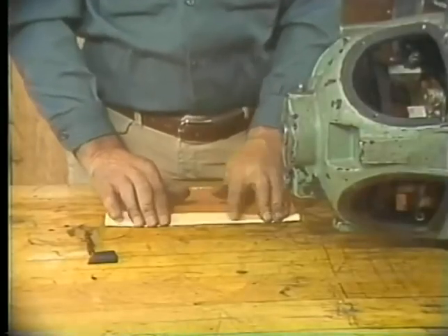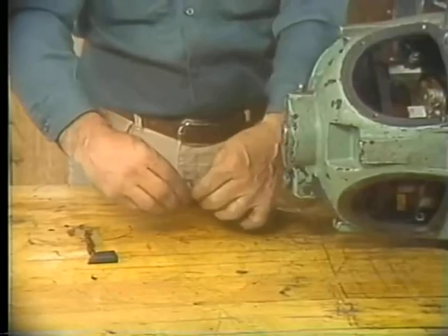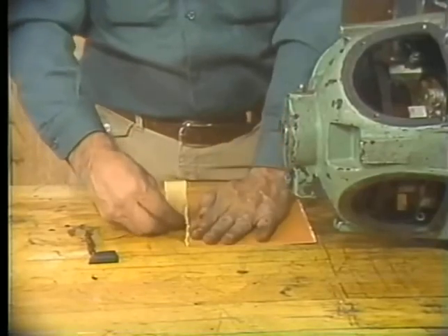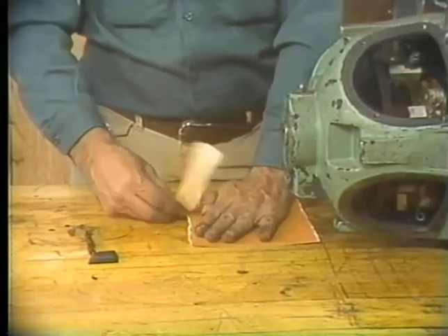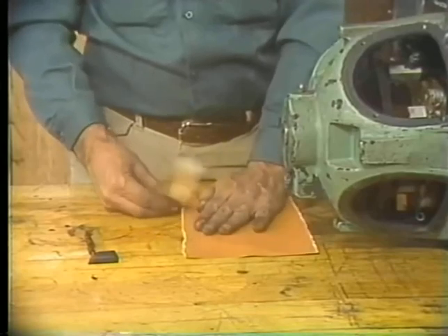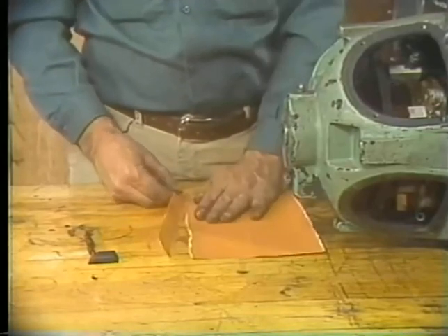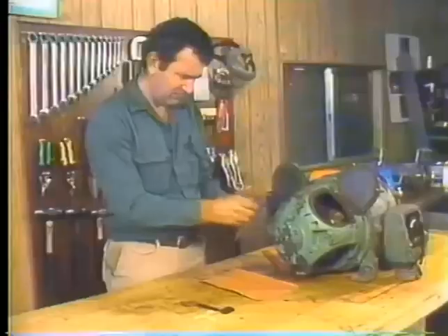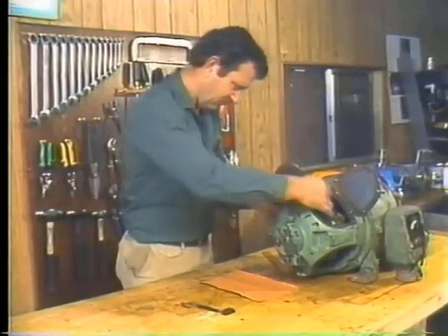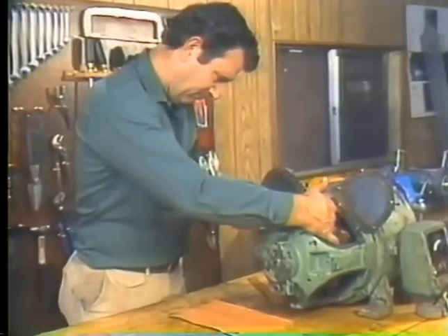Or you'll regret it. You see, emery particles are conductors. If they find their way into the area between the commutator segments, they'll short the motor. Okay? First, you tear a strip from a sheet of flint paper. The strip of flint paper must be at least as wide as the brush to be sure the entire surface is seated. Now place the flint paper on the commutator, flint side out.